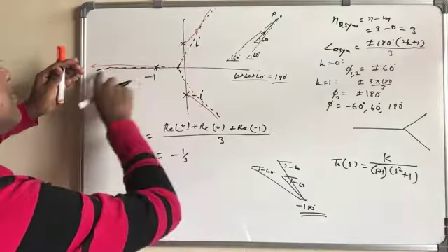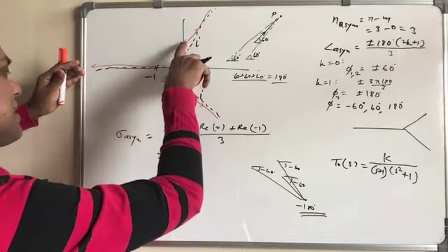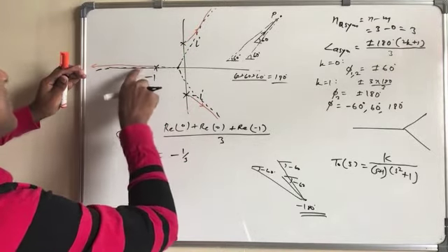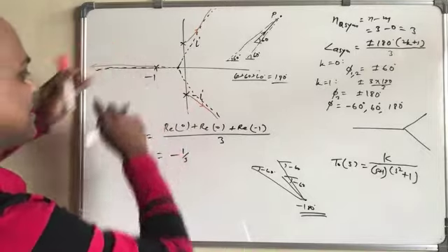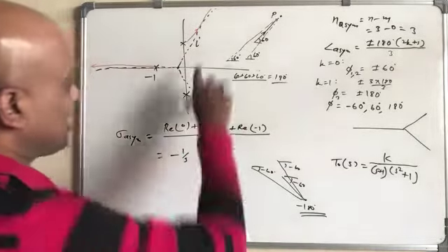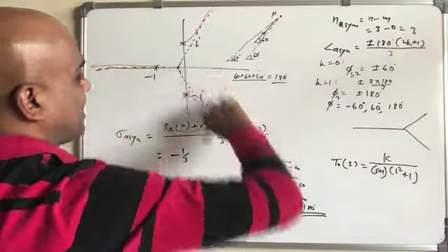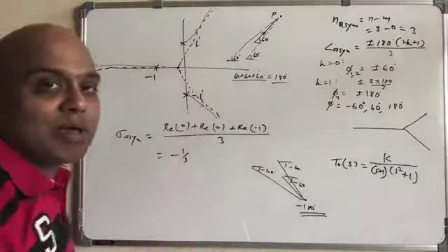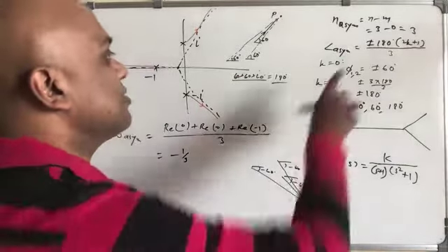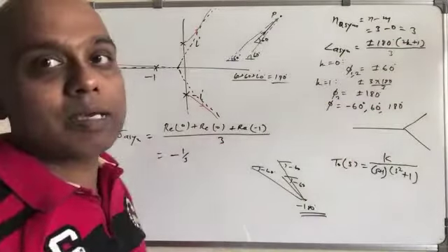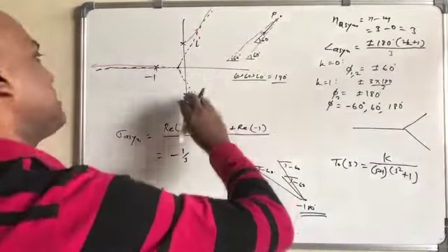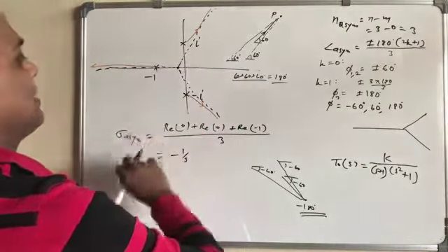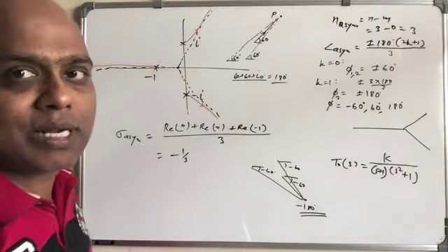Since these points are symmetric, it is 180 degrees everywhere on the real axis, because they cancel each other. However, if you are not on the real axis, then only when you equally divide that is it going to meet the condition. Hence you have this formula applied, meaning that it simply tells you that all the angles are equal, so there is an equal angle between the two. That's really what it tells you.